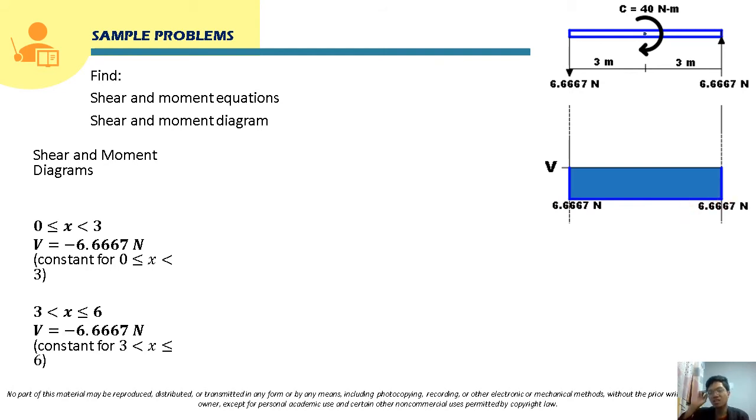As you can see here, this shear is just a rectangle, right? Because our applied loading here, class, is a couple. And if you go back to our discussion, if the load is a couple, its shear will be constant.